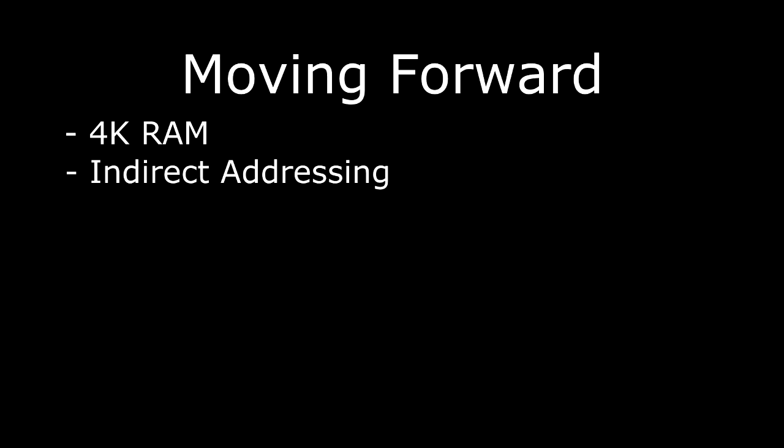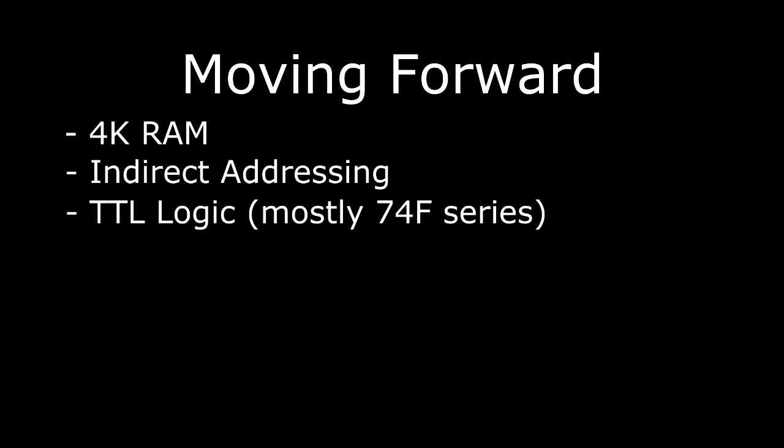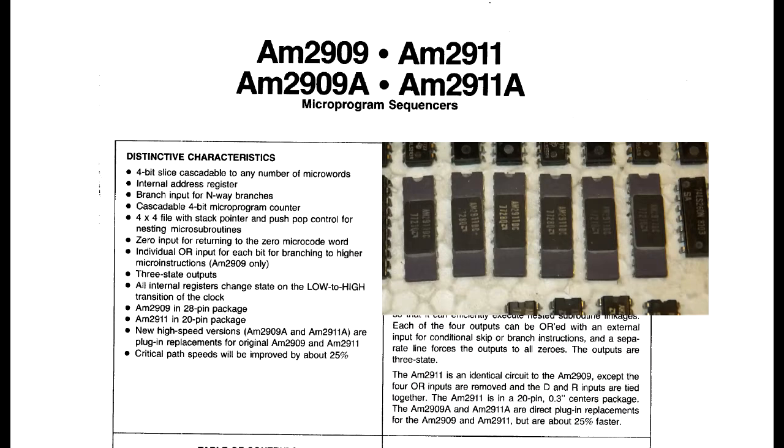What technology? I decided to stay with 7400 series logic for the most part, not use programmable logic, except, of course, the microprogram memory is held in programmable. In this case, it will be flash memory, which gives me a much better access time than that old EEPROM. I have some old AMD 2911s, which I could have used, but they're not the A version of the parts, so they're pretty slow. So I decided not to use those.